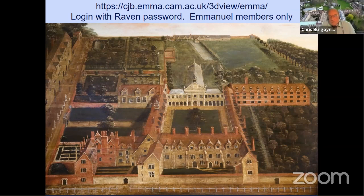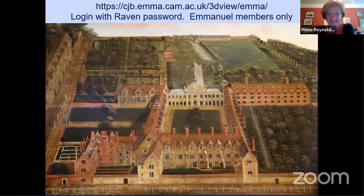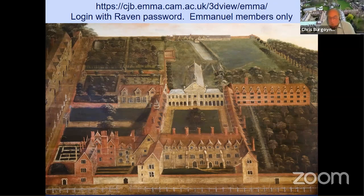Well, the drone doesn't have to be accurate. All you have to do with the drone is miss the building. Right, which is quite important if you've got a big cathedral. What the drone will do is take photographs, and the photogrammetry will then work out where the drone was. You do have to have some control points.